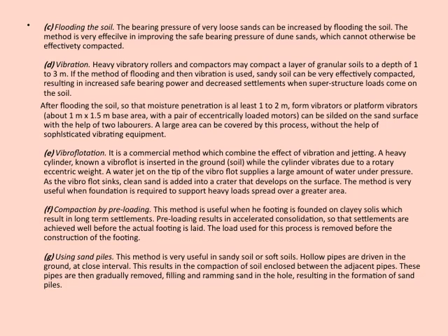Now, let's look at some effective methods to improve soil bearing capacity, starting with flooding the soil. This technique involves inundating very loose sands to increase their bearing pressure. It's particularly effective in dune sands, which are difficult to compact otherwise. Flooding helps to stabilize and densify the soil, making it safer for construction.